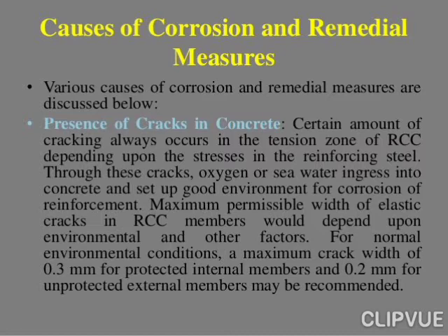Presence of cracks in concrete. A certain amount of cracking always occurs in the tension zone of RCC depending upon the stresses in the reinforcing steel. Through these cracks, oxygen or seawater ingress into concrete and set up a good environment for corrosion of reinforcement. Maximum permissible width of elastic cracks in RCC members would depend upon environmental and other factors. For normal environmental conditions, a maximum crack width of 0.3 mm for protected internal members and 0.2 mm for unprotected external members may be recommended.